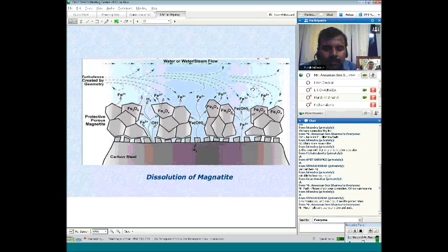So that is where people have associated this sort of corrosion with the mechanical disturbance in the water. Naturally, this sort of turbulence will occur downstream or upstream of the elbows, valves, or reducers. It was confirmed afterwards from the field information that yes, most of the FACs are occurring near the elbow joints, valves, control valves, and header joints, where there is a chance of increasing turbulence in the water.